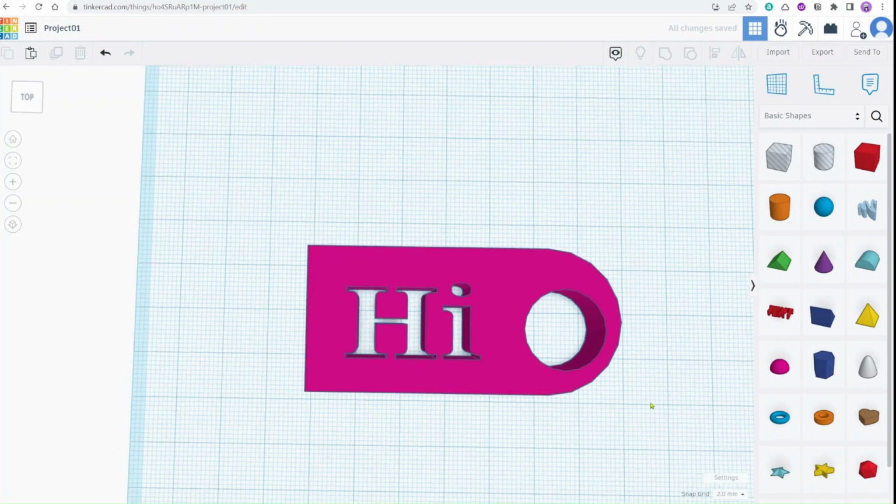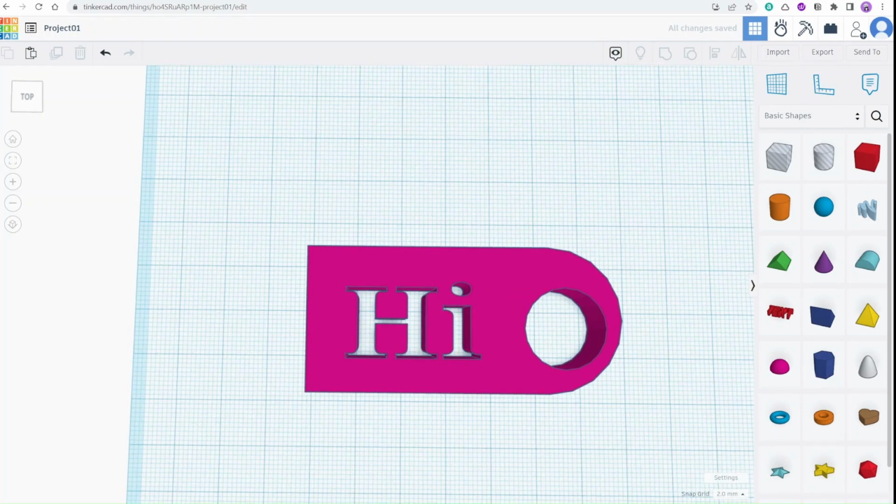Boom. All right. So what we learned today: the way that we can change the work plane setting by using these two settings and snap grid, right? And the way that we can copy an object by using Control C, Control V, and there was another way, right? Control D, which comes with all the parameter settings.